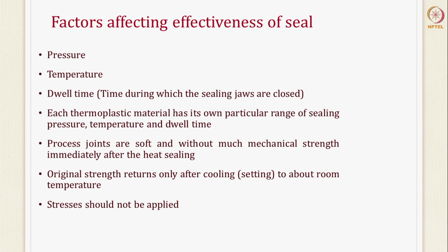One is the pressure. Another is your temperature. The dwell time, the time that you keep the jaws closed so that the package melts and fuses to each other, that is important. Each thermoplastic has its own particular range of sealing. Depending on the material you're using, you have to adjust the temperature of the sealer. And stress should not be applied. You see that it is sealed properly.